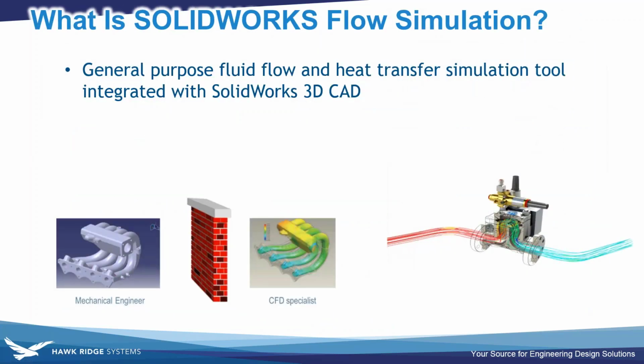So in case you're not familiar, Flow Simulation is the general purpose fluid flow tool for SOLIDWORKS. It can simulate the flow of gases and liquids in or around any solid geometry that you create in SOLIDWORKS. And it does the heat transfer associated with that at the same time. And basically it's set up to be a CFD tool that any design engineer can use. You don't have to have a lot of detailed expertise in using CFD or a lot of knowledge about how to mesh the boundary layer properly or what turbulence parameters to select.